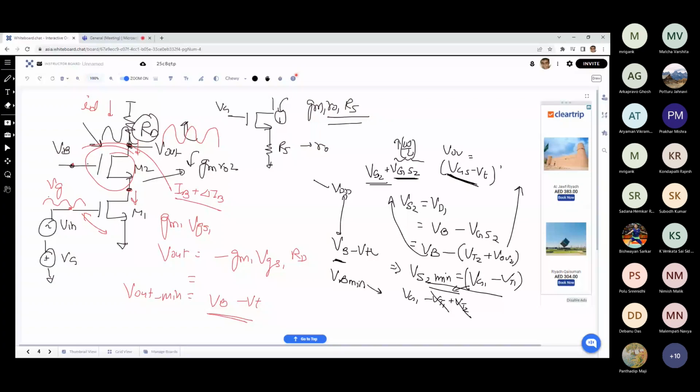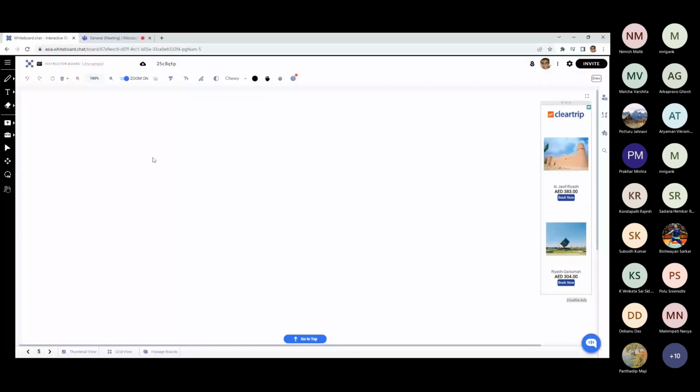I think by now you should have the answer. You must have read it. So what is the benefit here for this particular amplifier? Anybody checked it? Like, did you read it somewhere? Increased bandwidth because of less capacitance between input and output. It increases what? So the bandwidth.